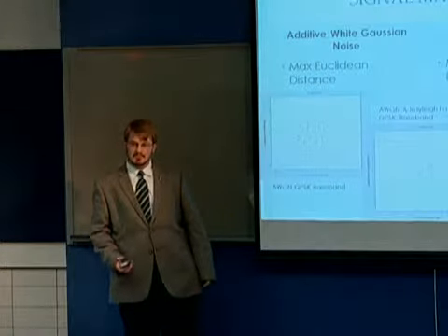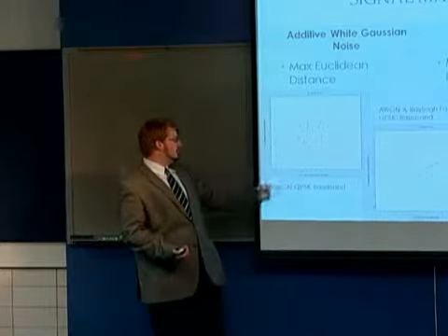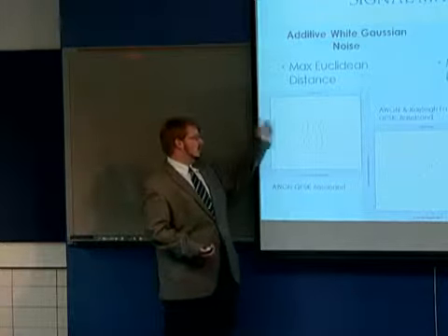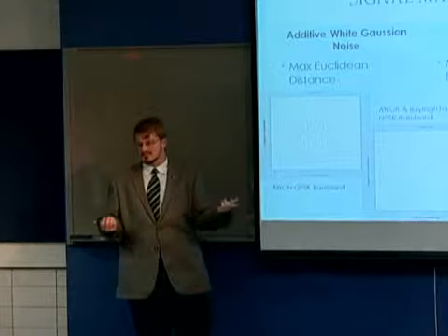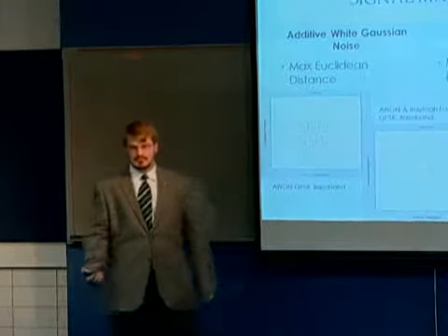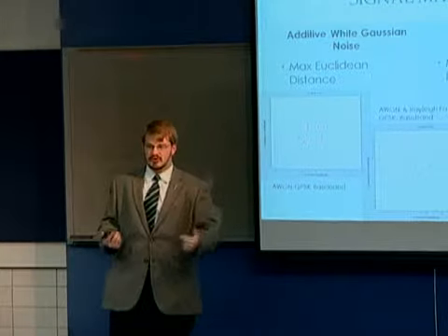Can you explain a little bit about this signal constellation and how the fading effect comes into play on these three different plots? You mean this is just a regular QPSK. I just took it for one. Well, what do these dots correspond to? They correspond to where the point has been moved based off of the channel response.